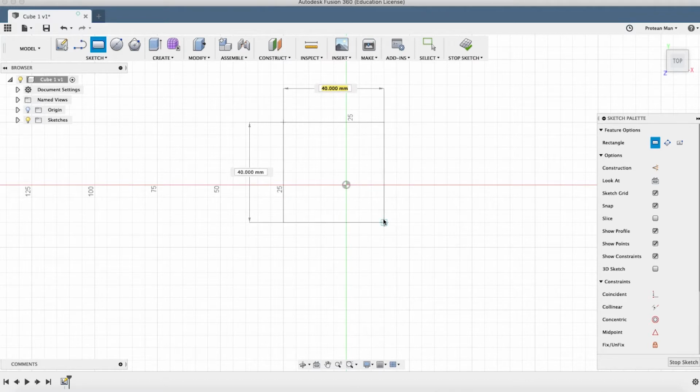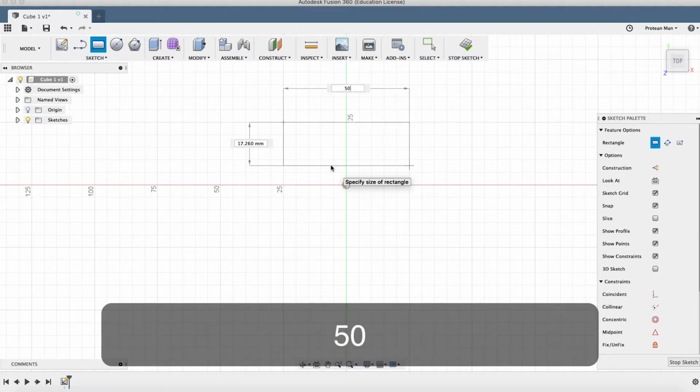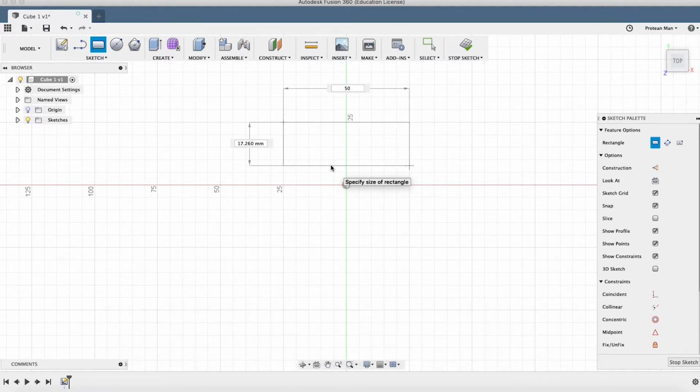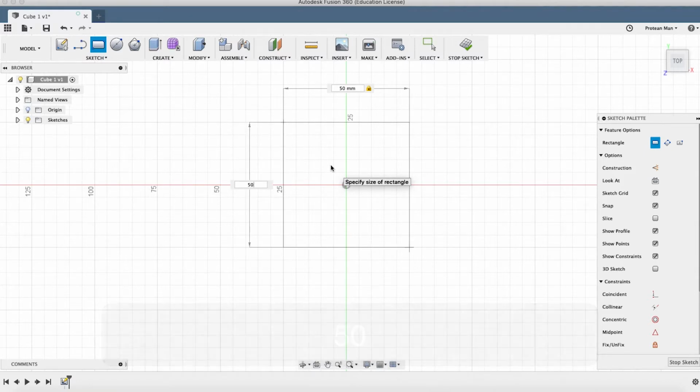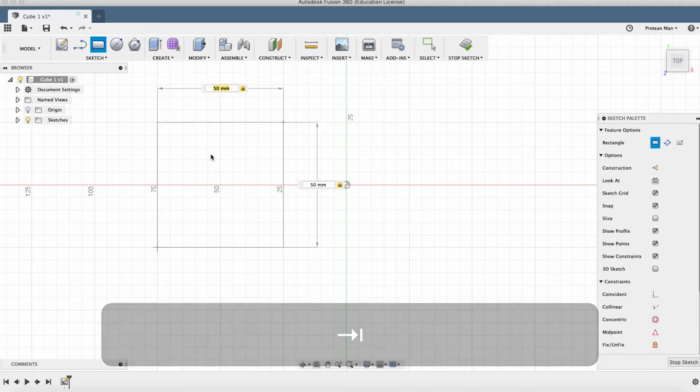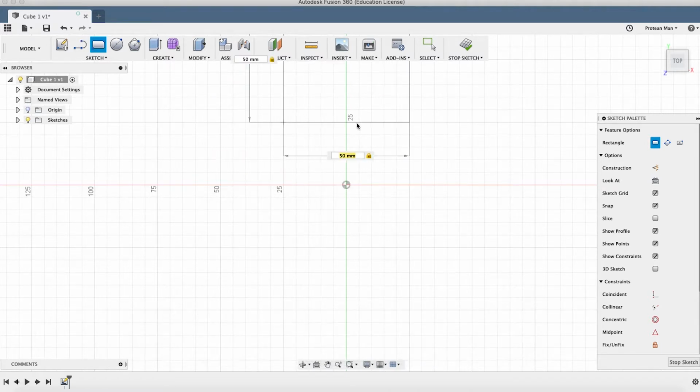Now if I go up to the green y-axis, go to the 25, and all the way across to where the 25 on the y and the 25 on the x, the red, meet up. That meets up here. It's a slightly thicker gray line. Just click on that point. It should snap there automatically. Click there, and as you drag down to the right, you're going to see this square start to open up.